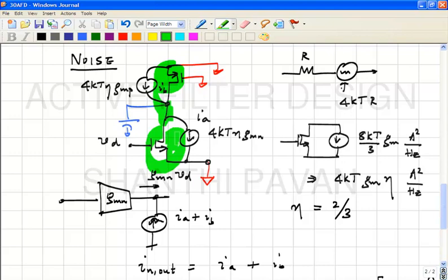However, the NMOS transistor is also producing a signal component, whereas the PMOS transistor is just producing noise without producing any signal current. So it makes sense that the transconductor noise performance is actually degraded by the PMOS transistor, which is why in the earlier discussion I had indicated that you want to make GMP as small as possible for noise reasons, right? But if you make GMP very small, the common mode gain goes up. Okay, all right, I will continue in the next class.